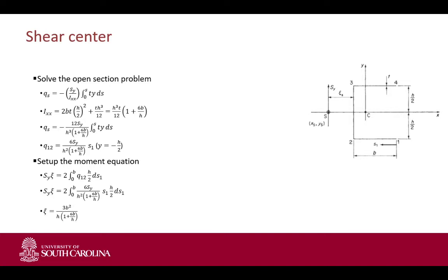We'll see that often, especially in closed and open sections, that the shear center will be, depending of course on the cross section type, outside of the cross section. And just keep in mind, if this was a real structure, you still have a transfer of loads. So this will be somehow connected to that location. A couple more things.